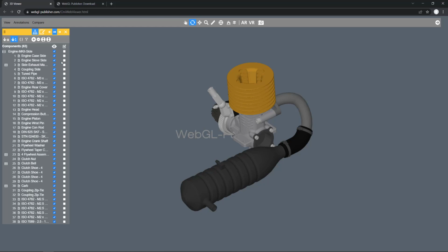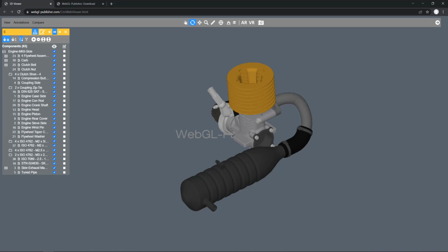In the default state, the model is sorted using the position numbers. This can be changed by pressing the button for an alphanumeric sort. Within a level, all multiple assembled components with the same name can be collected using the Collect Same Name button. Disabling the Show or Hide checkboxes hides or shows the corresponding components in the graphic area. Enabling the Select checkboxes highlights the components.